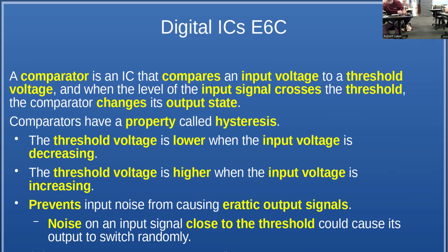So the amount of that hysteresis voltage determines how much noise immunity you've got. If you have noise spikes that exceed that, then you're going to get switching because of the noise.